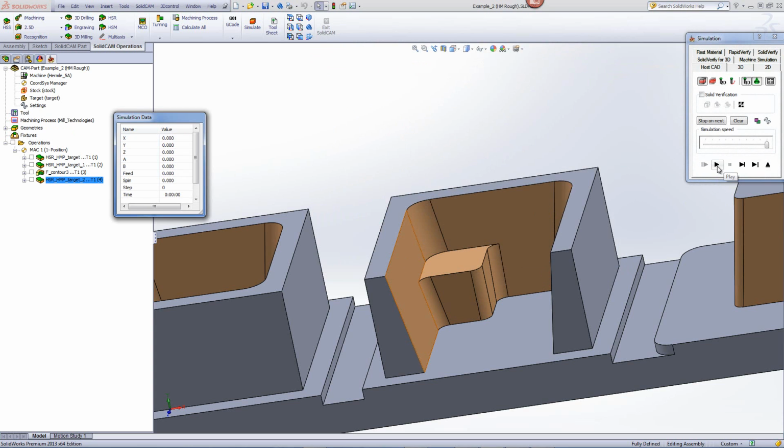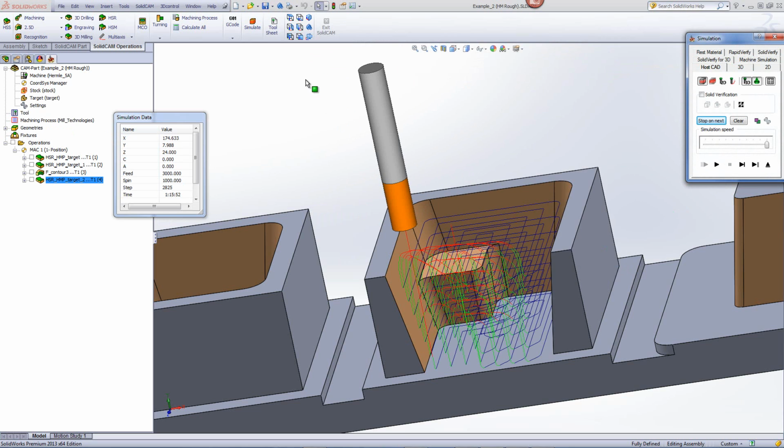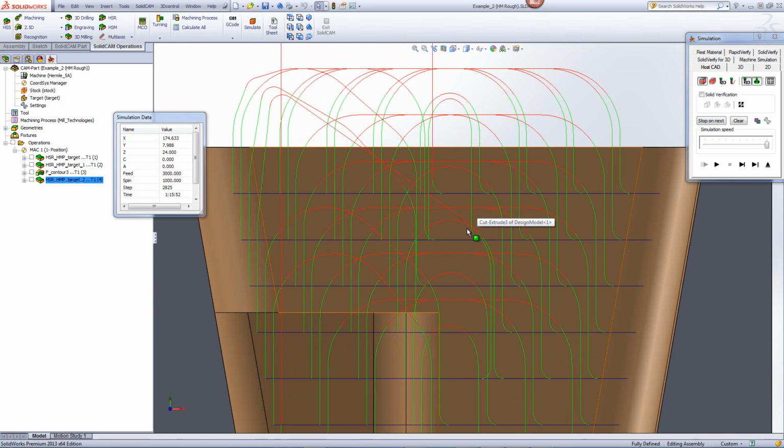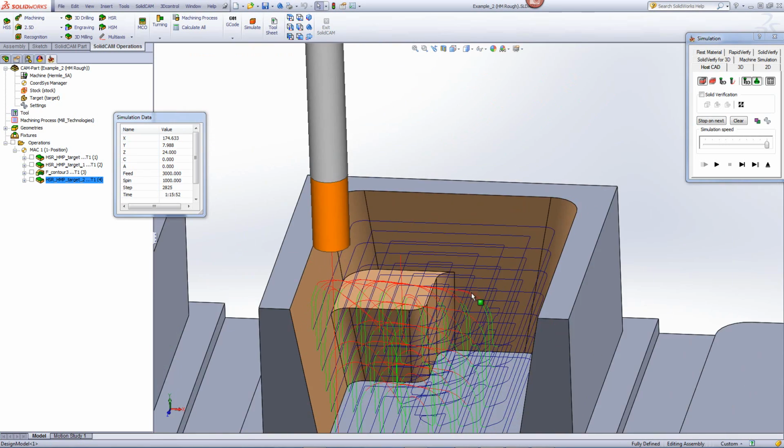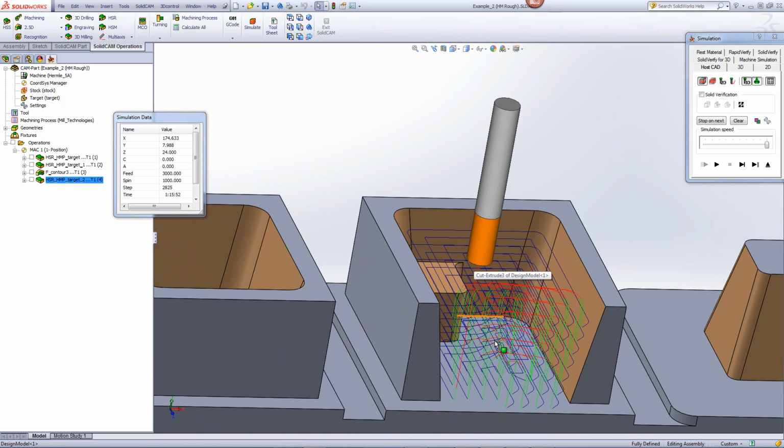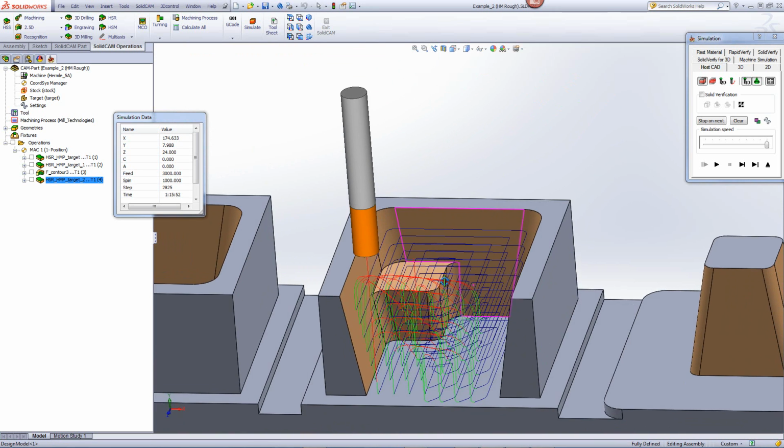You'll note that the tool path, if I look at it from the side over here, goes down every 7 millimeters. This step, this step, this step. The next step down here, note it's this particular case, it's leaving a lot of material over here. But I told it every 7 millimeters constant, so it's exactly what it did. Also note the tool path is actually really nice. It's going from the outside, like a regular offset cutting with a contour cut off on the walls itself.